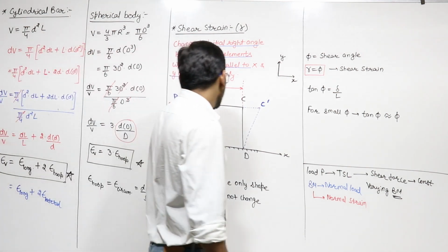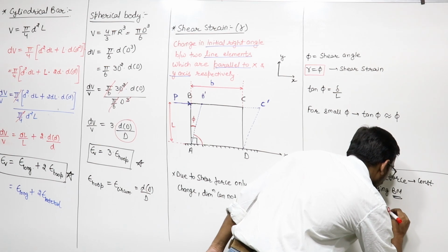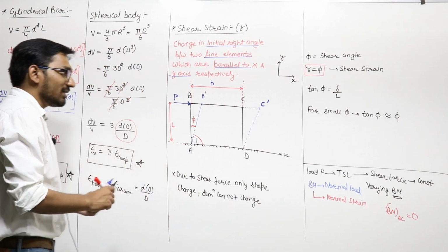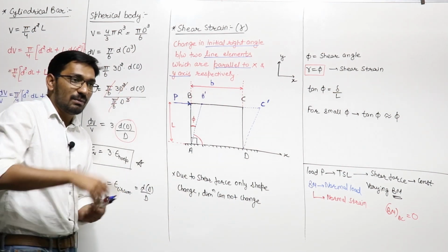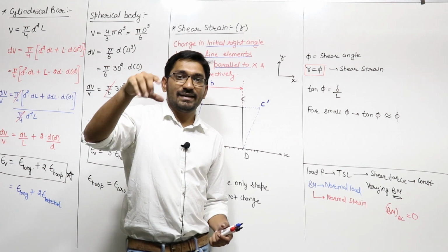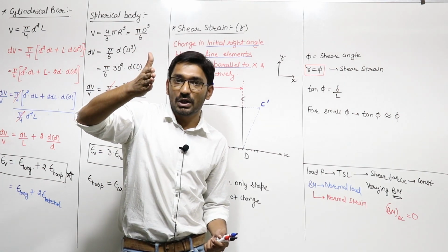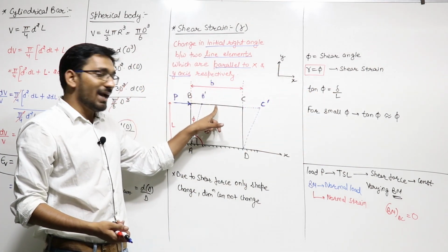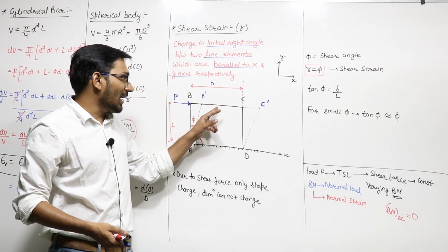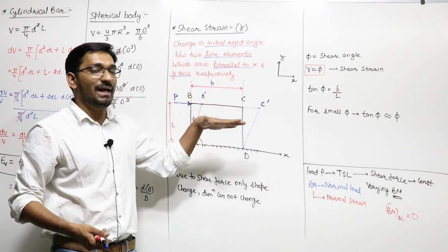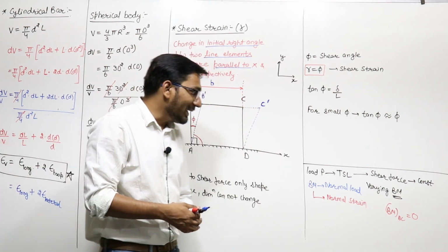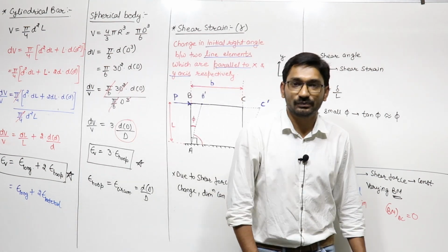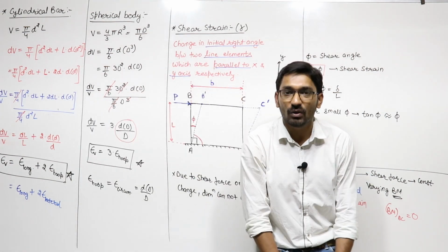And we know that this bending moment is maximum at this end. If I write the bending moment on BC, it will be equal to 0, because if you remember, the bending moment will be P into X. X is the distance of the point where you want to calculate the bending moment from the free end. This is a free end, so X here is 0, so the bending moment at this fiber, this BC plane, is 0. So if the bending moment at BC is 0, normal stress will be 0, normal strain will be 0.